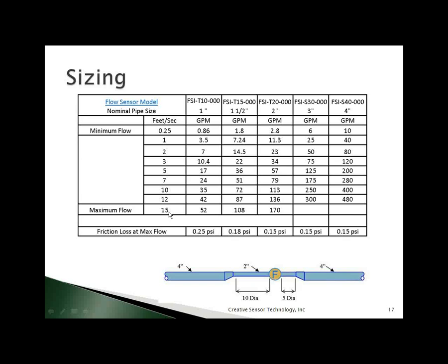There is no hard and fast rule that the wheels will come off the flow sensor if it goes faster than this. This is just what we selected as a practical limit. As you probably know, most pipe designers will specify that you shouldn't run more than 5 feet per second through PVC pipe due to water hammer and other stress factors. So you can easily see that the flow sensor can handle much higher velocities than the plastic pipe can.